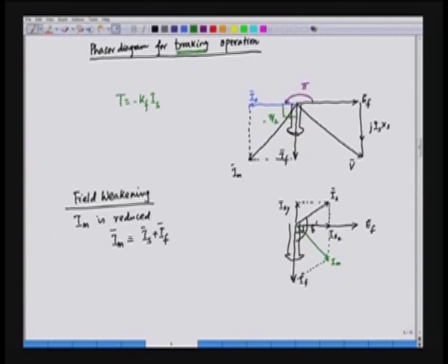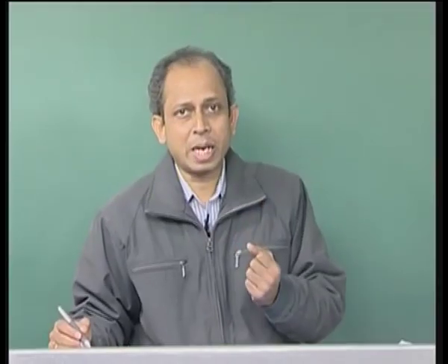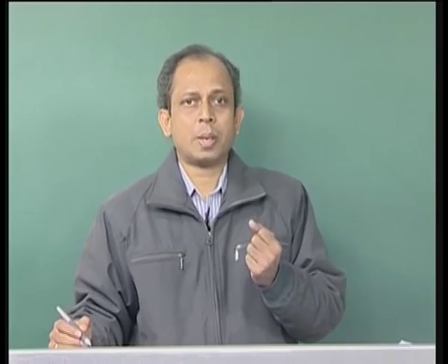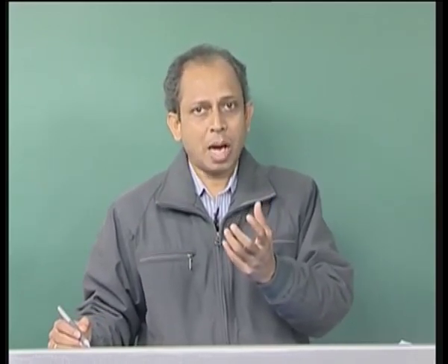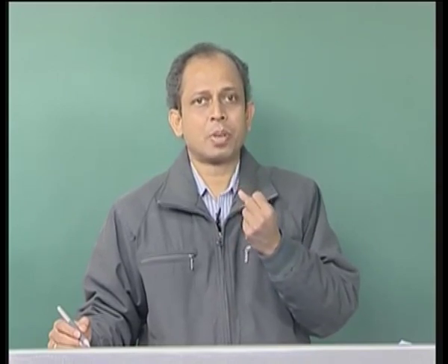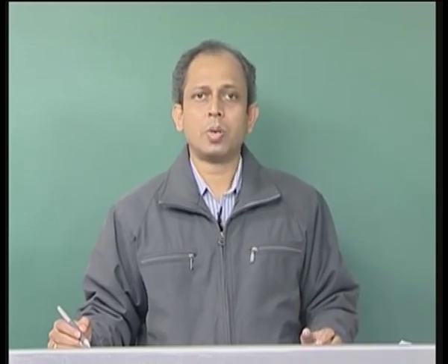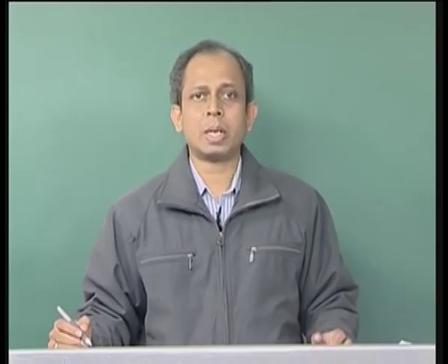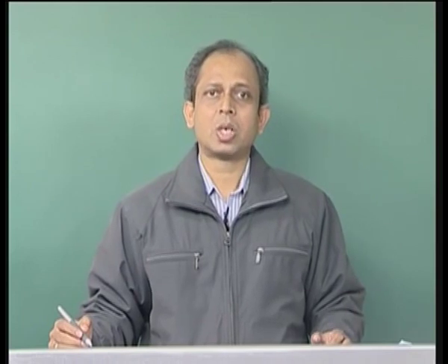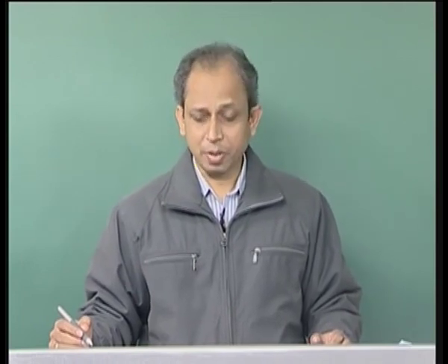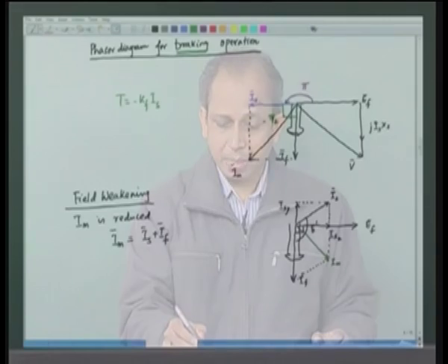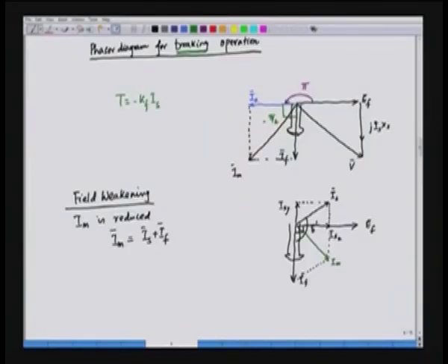So, when the motor is braking, the torque has to be negative, because the motor kinetic energy has to be brought out from the mechanical part and has to be converted into some equivalent electrical energy. So, during the braking, motor is in fact operating as a generator in which torque is negative, and that is reflected in a phase current. The phase of this Is is shifted by pi from the usual motoring position.